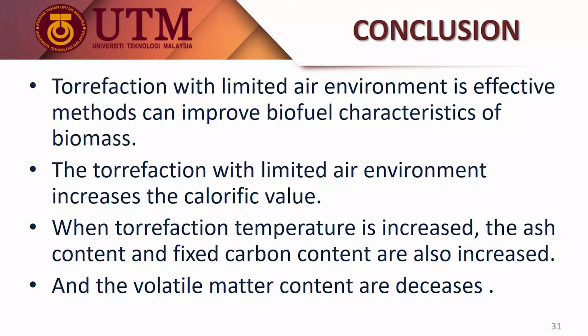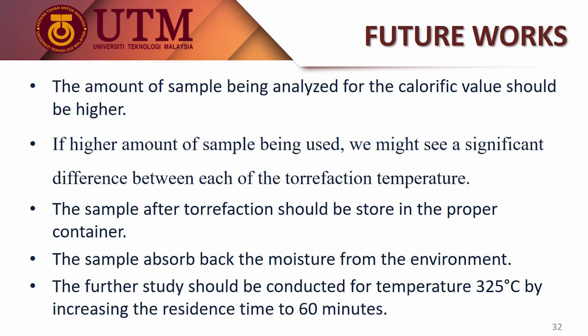For the conclusion, we can conclude that torrefaction with limited air environment is an effective method that can improve biofuel characteristics of biomass. The torrefaction with limited air environment increases the calorific value. When torrefaction temperature is increased, the ash content and fixed carbon content are also increased, and the volatile matter is decreased. For the future work, the amount of sample being analyzed for calorific value should be higher. If a higher amount of sample is used, we may see a significant difference between each of the torrefaction temperatures.